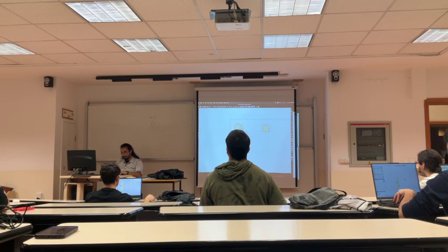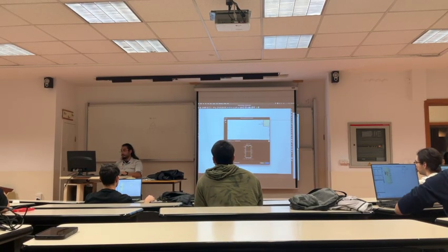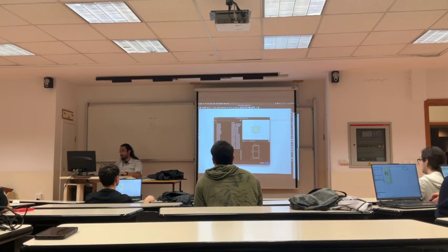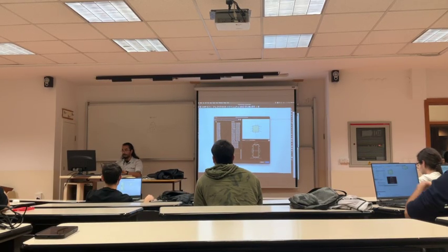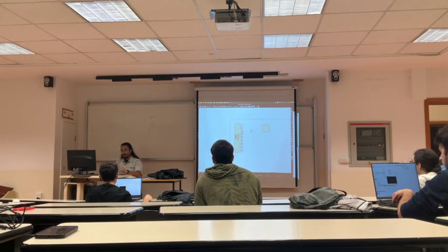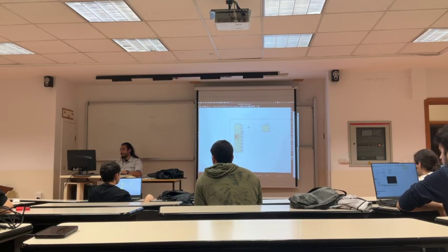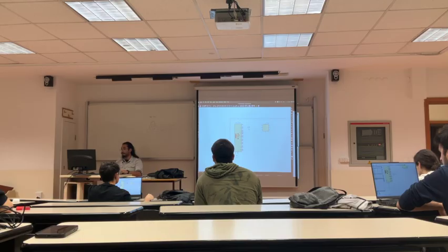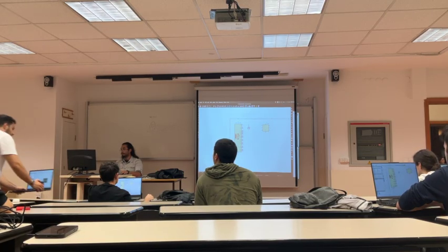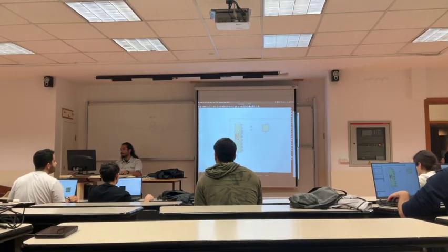I am going to put pull down resistors, and by that, I am going to press A. Then I type R to find the resistor. I click here, bam. Now I have a resistor. And then I click on R again to rotate it. Okay? I take it, I click on it to copy it and paste it again because I'm going to use two of them. As I said, this is a Type-C device, so we need two of each connection.